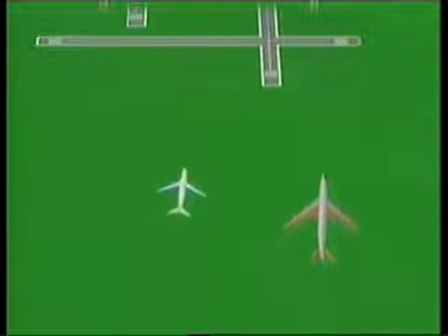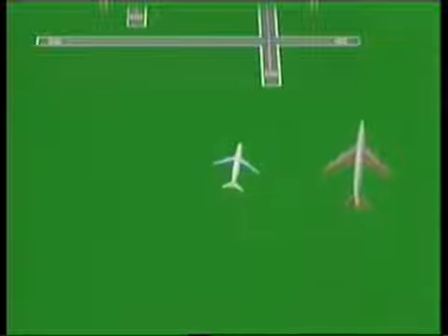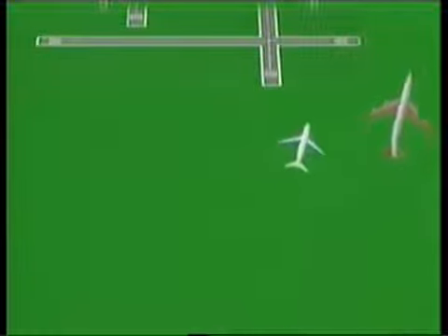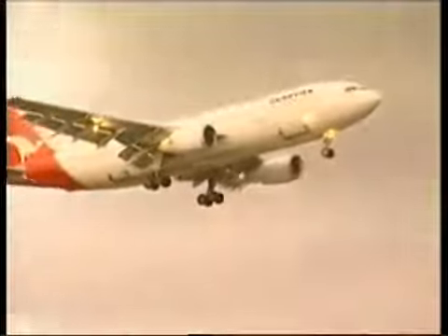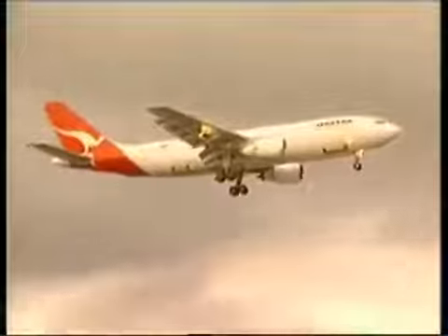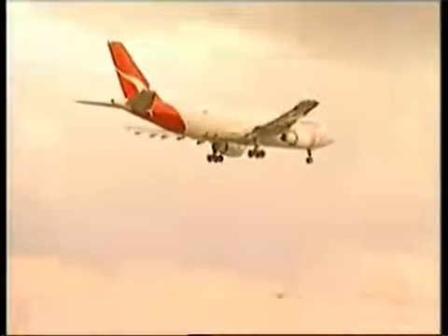Pilots flying an ILS PRM approach who get broken off the approach by the PRM controller must assume that a traffic conflict does exist. If the breakout maneuver is not carried out immediately, the results could be disastrous. The pilot will have little warning that a breakout alert is about to occur, because the aircraft causing the breakout is on another frequency, and you will not be able to hear the controller's efforts in returning that straying aircraft to the adjacent localizer.